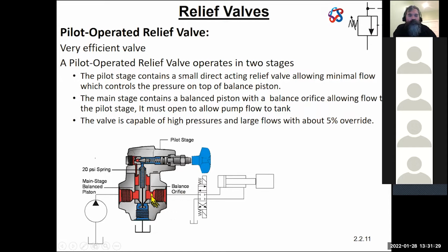So a small fraction of fluid can escape through that into this area. This is why at the moment, when this valve is closed, it's pressurized, because there's no fluid flow. It's virtually incompressible. If I put high pressure at one area, according to Pascal, I've got equal pressure throughout that fluid if it's contained, and the fluid here is contained. So this pressure up here is fairly high. There's a wider channel up here going back to the poppet and acting against this valve.